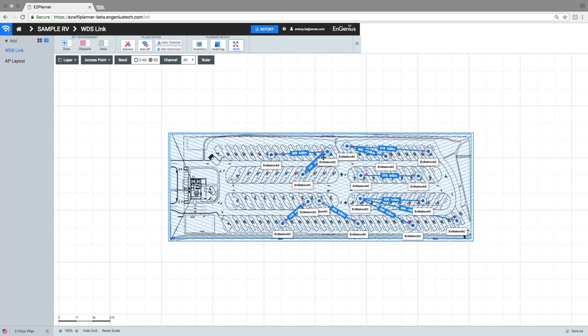As you say, these are end station ACs. You can see this is not an actual point-to-point, it's a point-to-multipoint, and it's a little bit off, but it's close enough that it's able to get good signal and good performance there. And this one is too far from each other, so I had to create two units, 2 point-to-points, as opposed to 1 point-to-multipoint. This one you can see is 3-to-1, which is the ratio you recommend, 3-to-1, no more than 4-to-1.